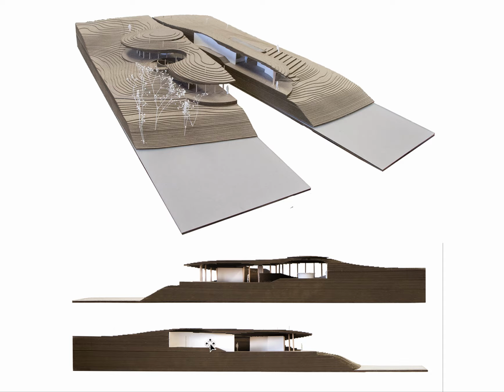And so what you're seeing is splitting this, and you're looking inside. And now you can see these are those contour lines, all represented as a single piece of chipboard. And the thickness of this board, if you want this model to scale properly, needs to be the thickness of your contour.